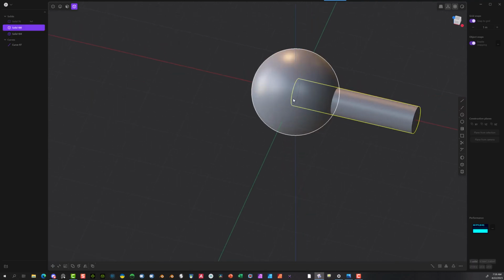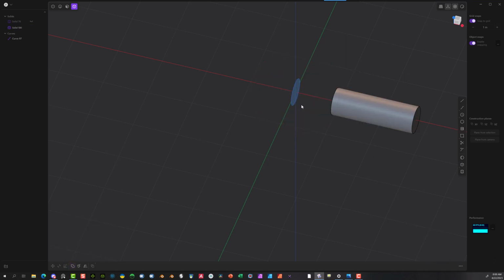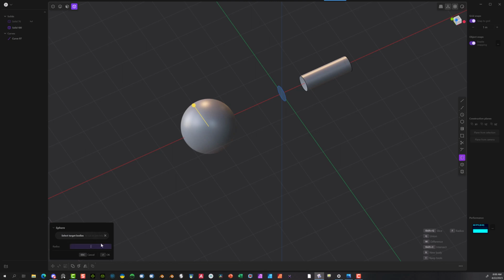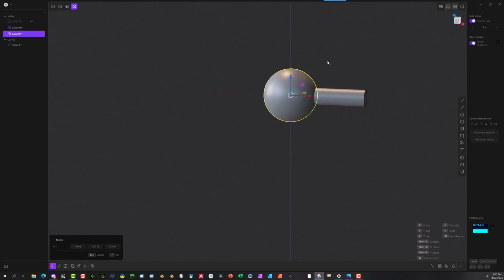Select this object. Select this object. I'm going to hit the Q key. Say OK. So basically I cut exactly at 0.94, and then I'm going to cut 0.96. So let's go and do this again. Hit the sphere. Again, let it drop. This time it's going to be 0.96. Say OK. Same thing, hit the G key, move it in to the center off of this.